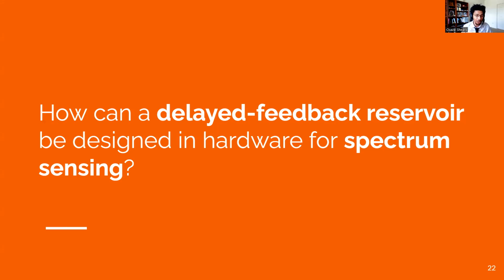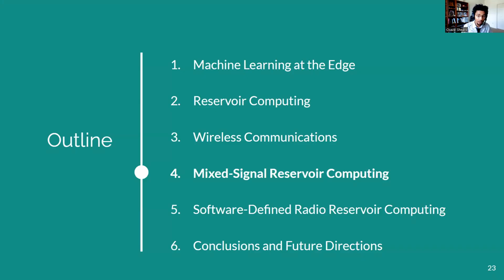So after all the validation and the studying between the software-defined radios and the problem, we come to the main research question here, which is how can we develop this particular delayed feedback reservoir model in hardware for spectrum sensing? We did two different approaches to realize this. The first was a mixed signal reservoir computing approach, and the second was a software-defined radio reservoir computing approach, where we incorporate that hardware onto the BladeRF itself.